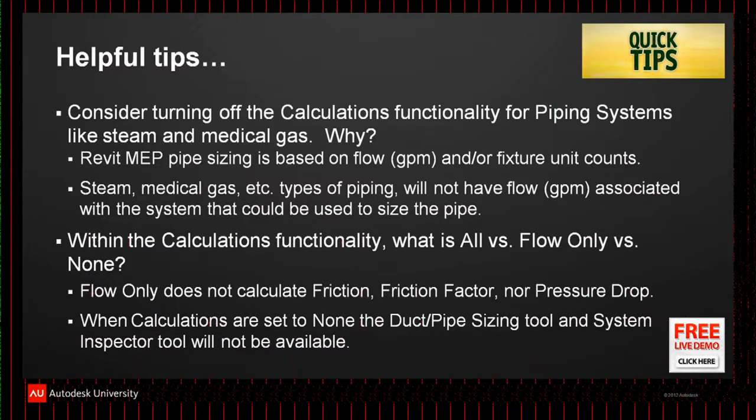The other thing is that you can actually limit what you want to see with those calculations. You can set it up for all, you can set it up with flow only, or none. With flow only, it's basically going to eliminate friction, friction factor, and pressure drop. So the other calculations aren't going to be in there.